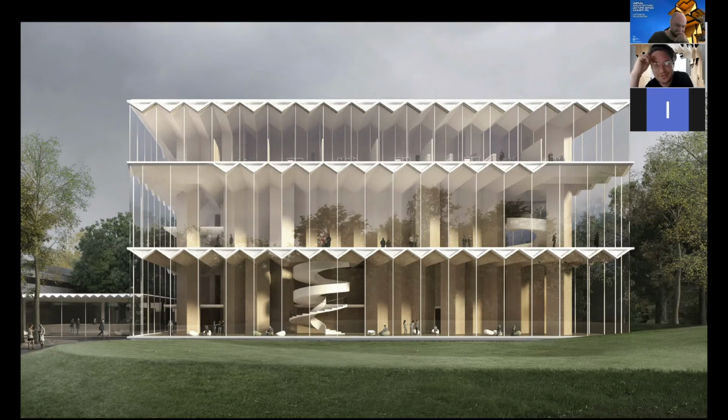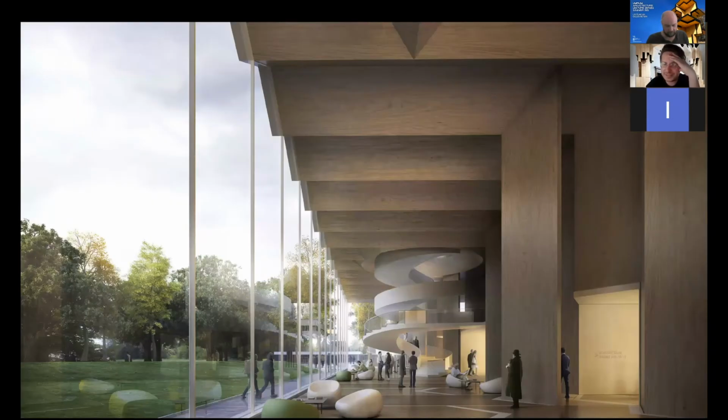It's quite funny that, of course, we were willing to compromise a bit to win the competition. So we were like, yeah, sure, the timber sheets on the top floor of the building will have a different dimension than the ones at the bottom, because the ones at the bottom are carrying much more load. But then our engineers, Bollinger Grohmann, stipulated that actually, because of fire regulations, the timber had to be the same dimension at the bottom and at the top of the building, because the fire regulations override the structural concerns. So again, I think it's quite amazing that the whole building is kind of primitive,